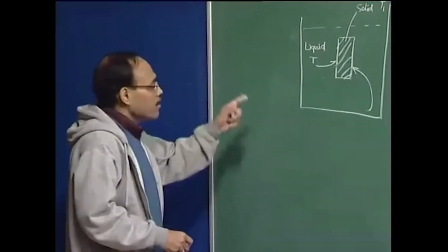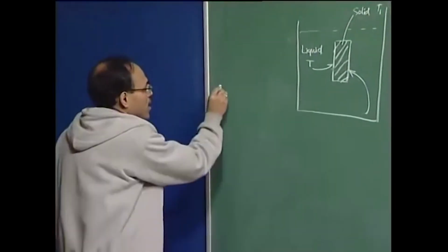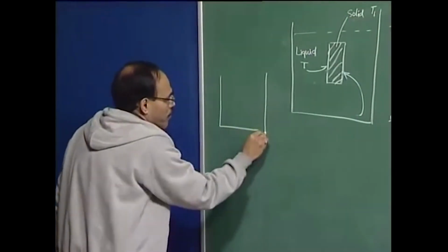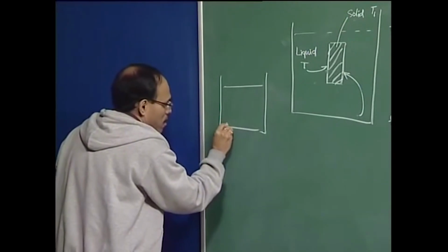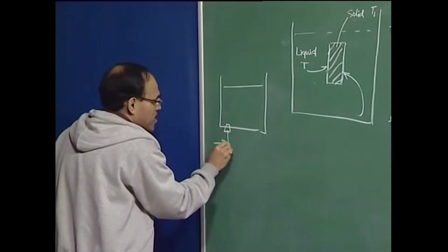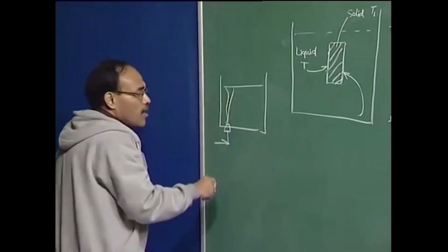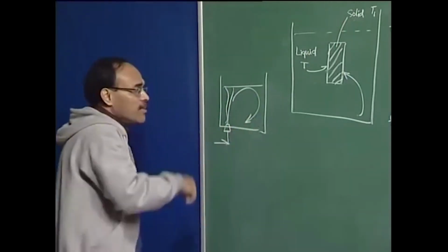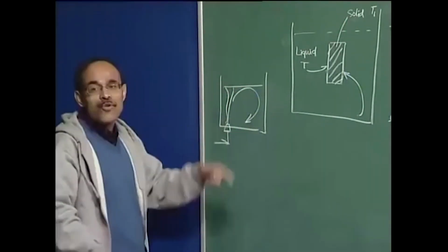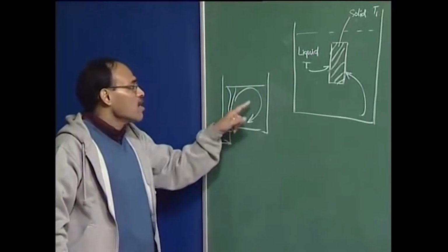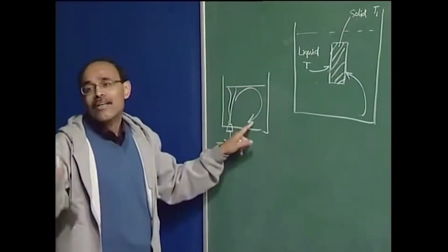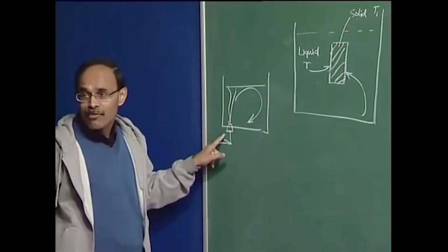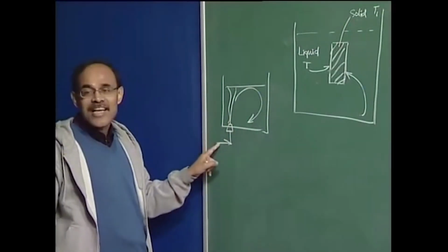So, therefore, in the context of steel making, I would say if I have a ladle which contains liquid steel, and I have a porous plug here, and I stir the contents of the ladle, okay, and there is a motion, and this motion is going to aid the distribution of heat in the system. So, heat will flow from one point to another point due to convection, of course, and that convection is going to be forced convection, and the origin of forced convection here is gas injection.